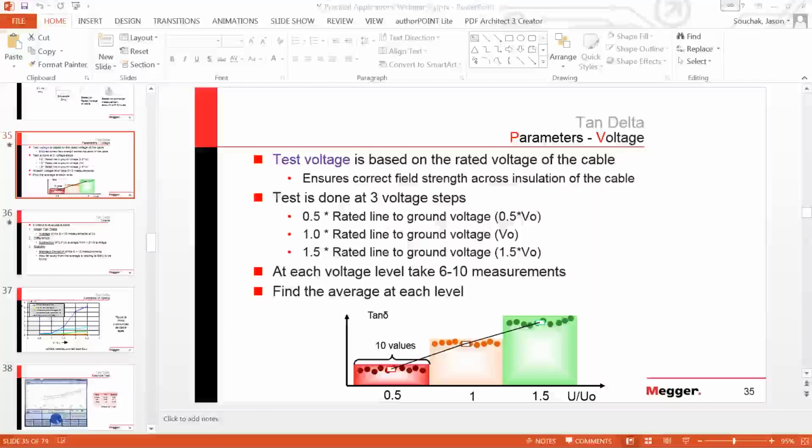Okay, it's basically coming down to the temperature or loading. Typically, loading equates to temperature because I have more load on it, I have more resistance, so I get a higher temperature. And the aging of cables, these aging processes that we have in the cable, are basically chemical reactions that change the polymeric material, or that change the paper when I have paper cables, oil insulated cables. So you can typically say that for every 10 degrees change in ambient temperature, the reaction will double its speed.